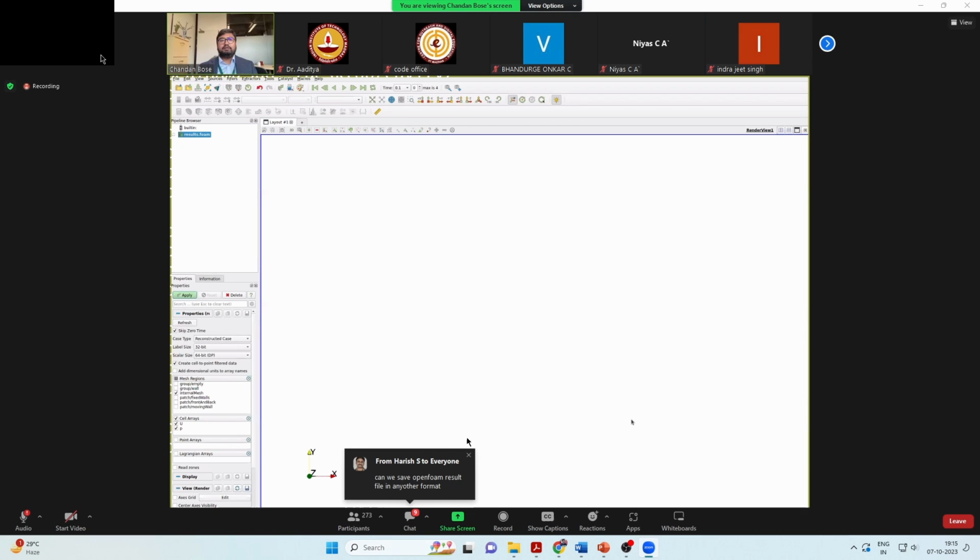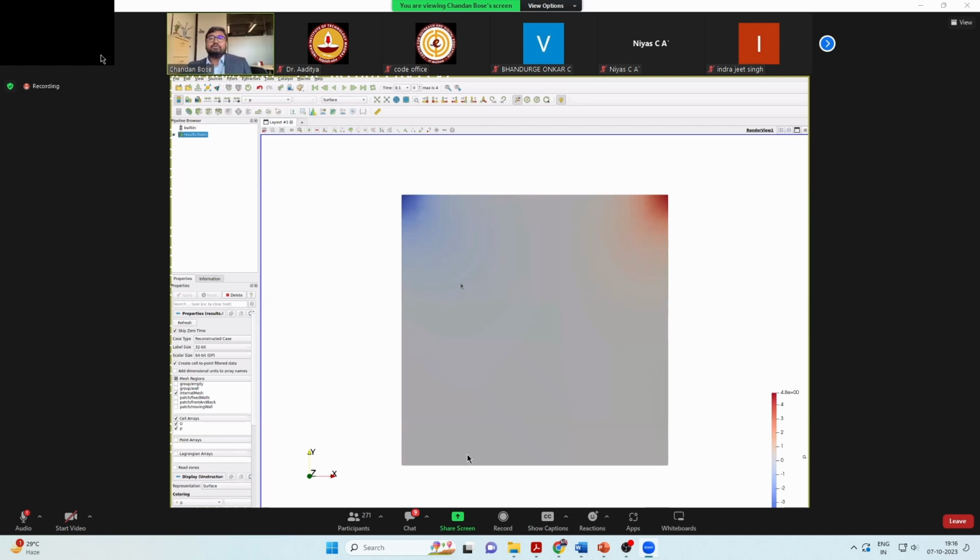results.foam file. And now to load the data into ParaView, we have to first apply, of course. By applying, we see the results. Now I will show you some basic uses of ParaView so that you can get started with the post-processing of your first simulation, hopefully. First of all, you notice that it shows you the time value of 0.01. That is the default case for ParaView.